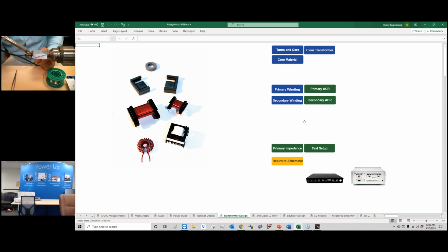And we're melting through the wires. So these are solderable wires. Makes that construction a little bit easier. And you can get all kinds of solderable wires. And I don't mind using a solderable wire in this application because if it fails, it just shorts the primary or the secondary and your converter stops working and there's no danger.